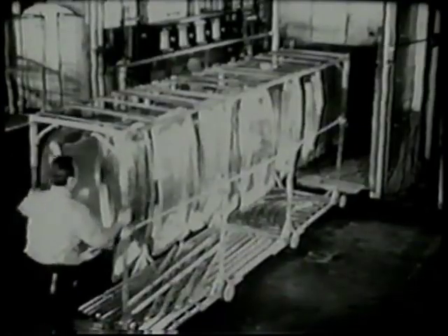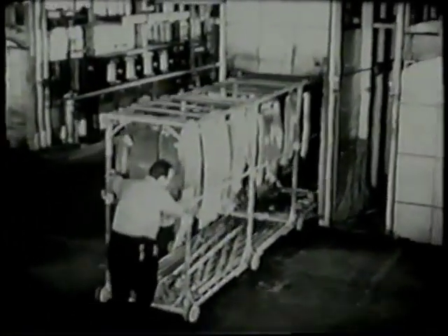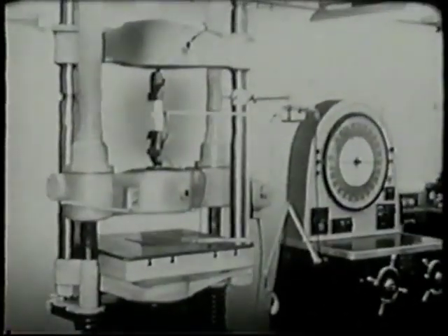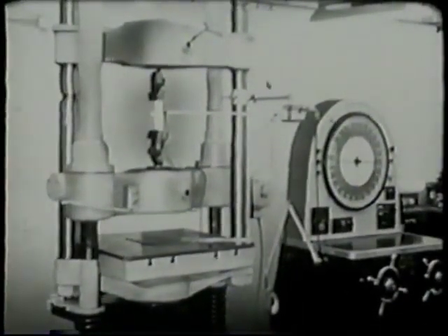Certain alloys age very slowly at room temperature. To speed this process, they may be reheated in an air furnace. For example, alloys 53S and 61S are aged at a temperature of from 315 to 325 degrees Fahrenheit for a period of from 12 to 18 hours. Through refrigeration, age hardening may be retarded in order to keep parts soft enough for forming operations. For example, by refrigerating 24S rivets, their driving characteristics may be retained for several days.